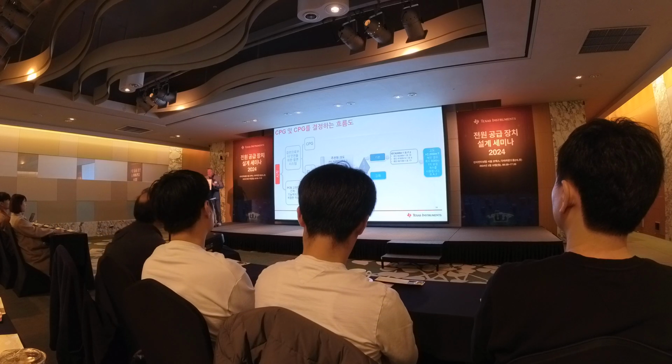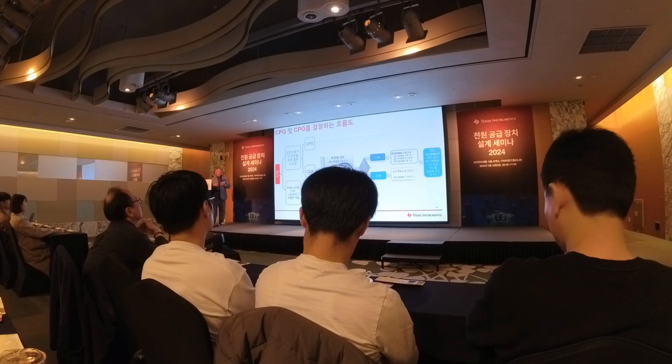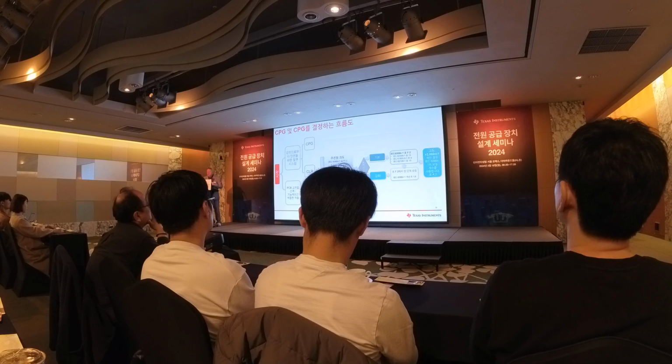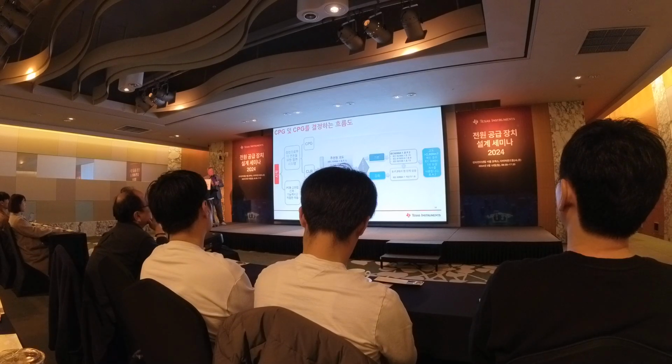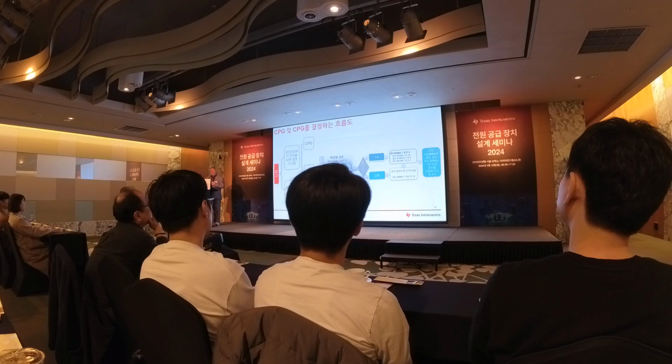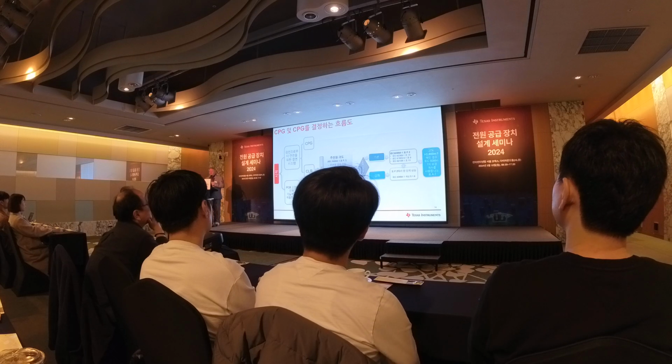Okay, next, if I determine it needs to be reinforced isolation, then I can refer to one step higher from table F2. So if I determine on table F2 that I need a certain spacing, but then it needs to be reinforced, I basically just go to the next level down of spacing.